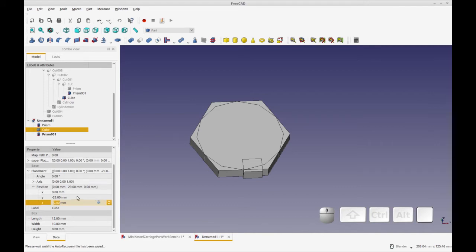And then we're going to move it in the X direction. We want this centered. It's 12 wide, so we move it to -6. Okay, so that's an easy centering. So that's the position we want. The depth of this is not really very important. The axis in here will be the nuts.